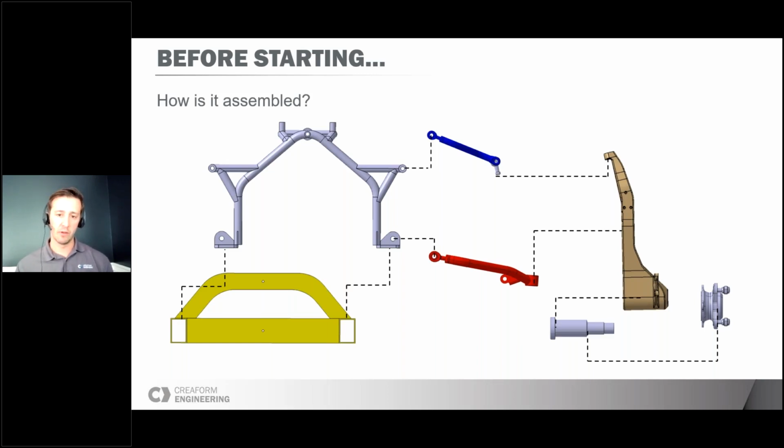This is the role of the upper arm, which is attached to the subframe again, but you have another ball joint at the top over there that attaches to the knuckle. And then finally, within the knuckle, you have really two important parts, which is the spindle, which really supports all the wheel assembly, and on it comes the wheel bearing on which the wheel will be attached.